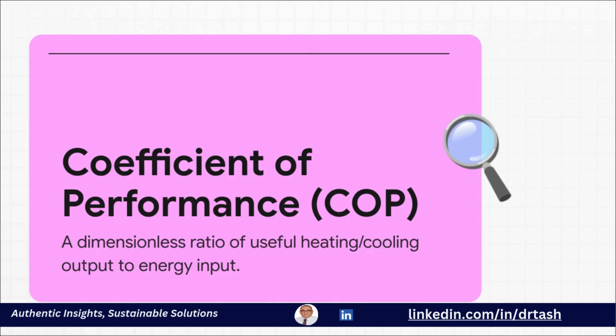For a chiller, that's the heat you're pulling from the evaporator divided by the compressor's work. For a heat pump, it's the heat you're delivering. It's our absolute baseline for thermodynamic efficiency. Higher COP, better performance. Simple as that.